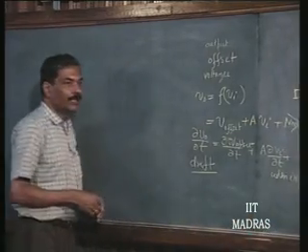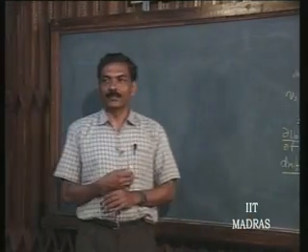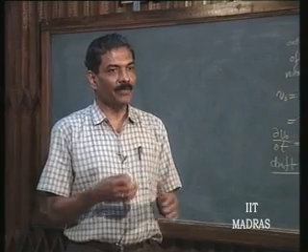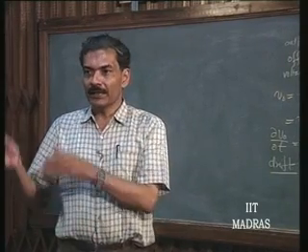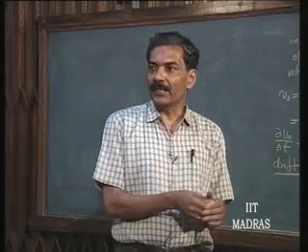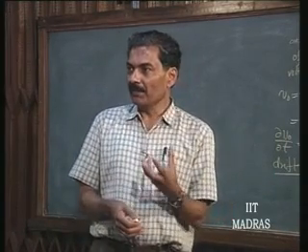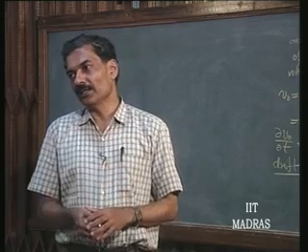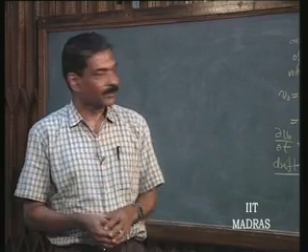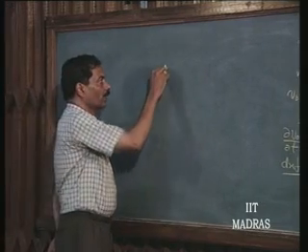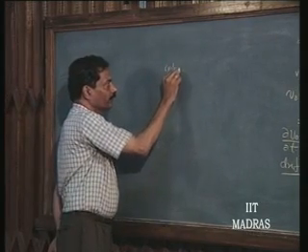So, how do we measure this offset? How do we come out with a design parameter, so that we can say this differential amplifier or op amp is better than another differential amplifier or op amp? That measure is another important parameter associated with op amps or differential amplifiers. So, we will come out with what is called the input offset.